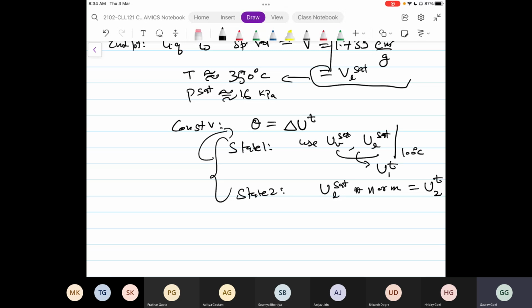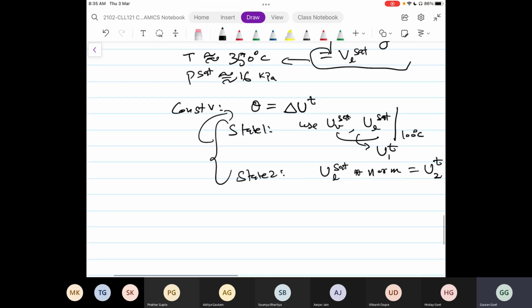All right, so now why is this relevant? That we have discussed in a different problem. In the lecture class I've discussed why this calculation is very important for design, but it's not important for water, because water is not that volatile. It has a high heat capacity, so its temperature is changing slowly, its properties are changing slowly. If I have some flammable liquids, some hydrocarbons, for them this becomes a very important storage problem. That we have discussed in the lecture. I will show you some maths here.